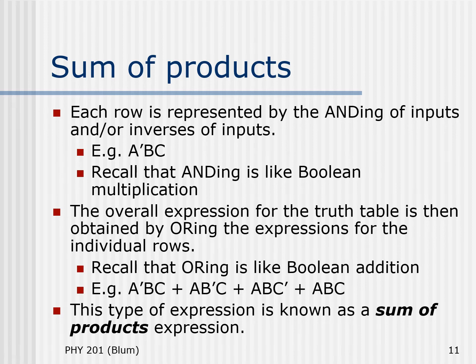To make the overall expression, we're going to take those expressions that corresponded to 1s in the outputs, and we're just going to OR them. So our majority rules expression will be A prime B C, or A B prime C, or A B C prime, or A B C.